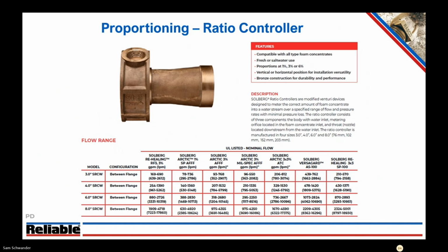So these devices we're generally using with fixed flow. So something like a deluge system, something where you have monitor protection around a diked area or a truck loading rack, something like a foam maker or foam chamber on flammable liquid storage. So even though we have a wider range of flows here, it's something that we're using where we know what the flow rate is for that system and it's not necessarily going to change.